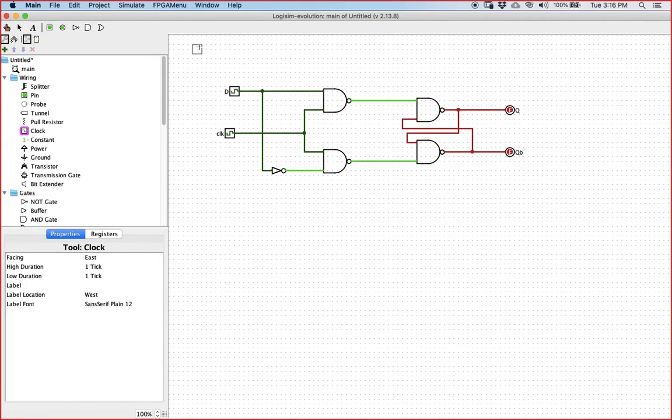But to run it you need to have one global clock which is just 1 tick. So this should be named as SYS CLK. This is necessary to do the simulation. So basically this is the global clock. What it means is this is 1 tick.